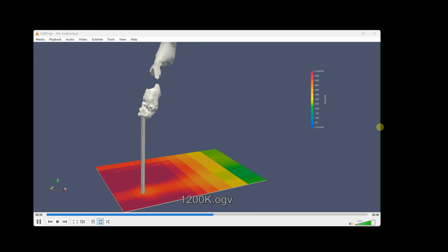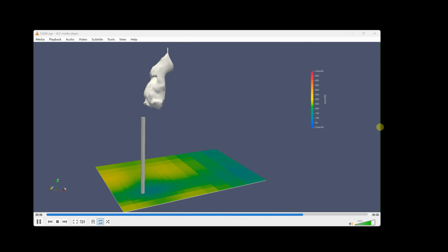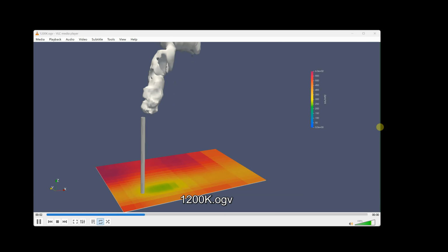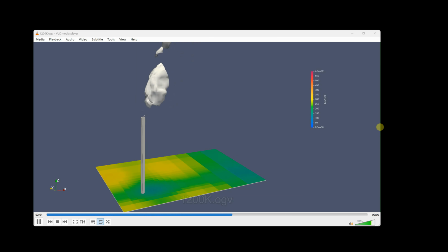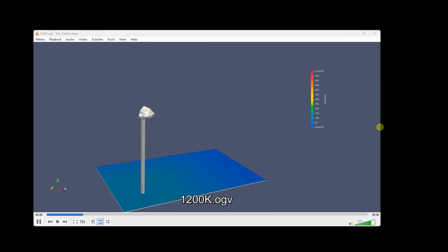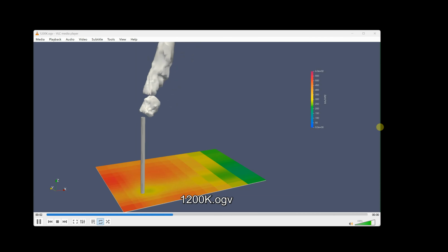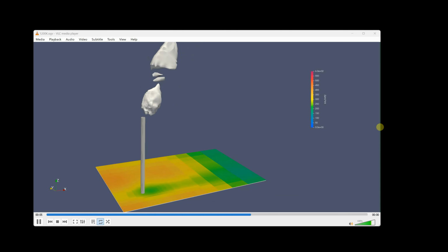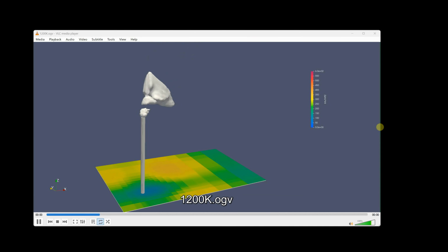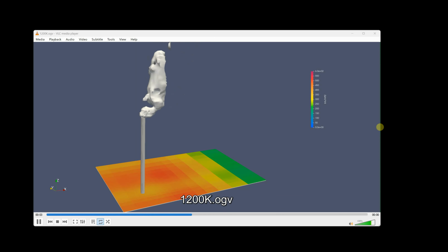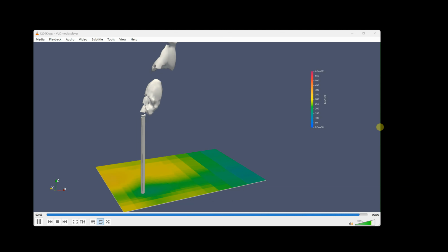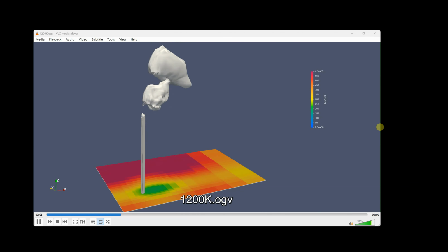Now, hydrogen flare or hydrogen gas in combustion is actually somewhat difficult to model because the density of the gas is very low. It's say 1/14th that of air at room temperature, and when you heat it up over 2000 Kelvin, it's going to be significantly lower than the surrounding air. So right at the edge of the flare in the combustion zone, you're going to have very steep temperature gradients, and that corresponds to steep density gradients. Both of those result in a fairly computationally challenging situation.